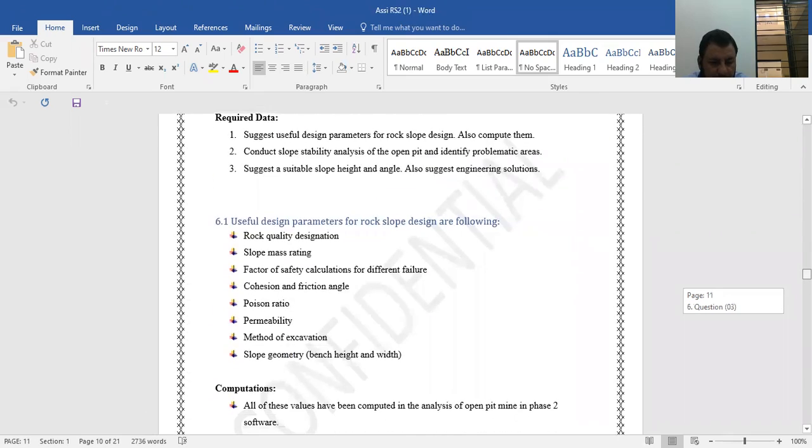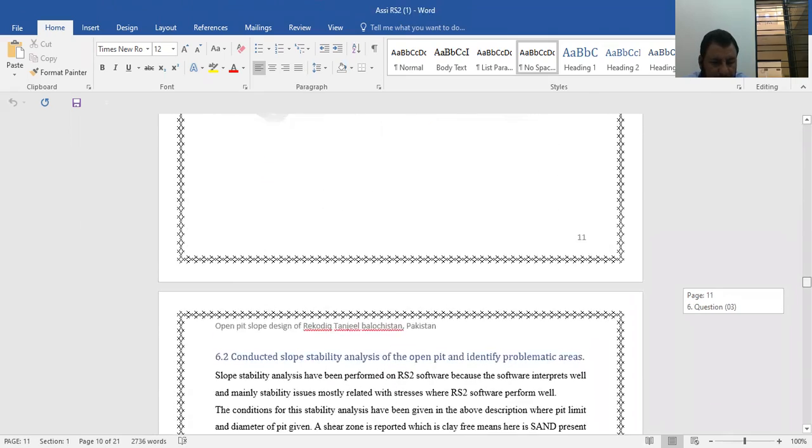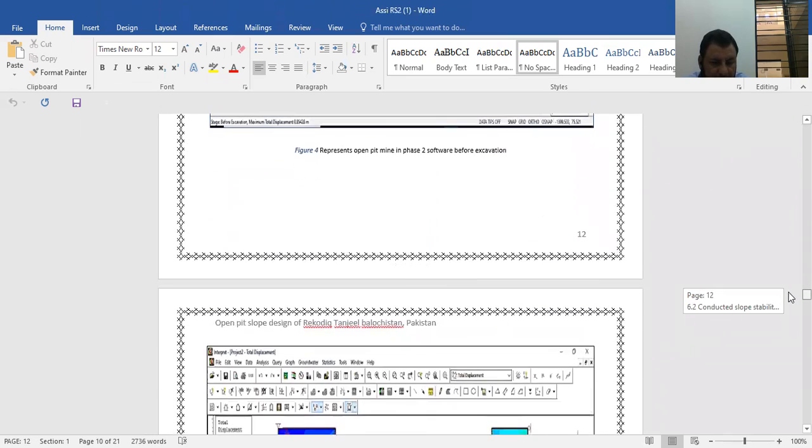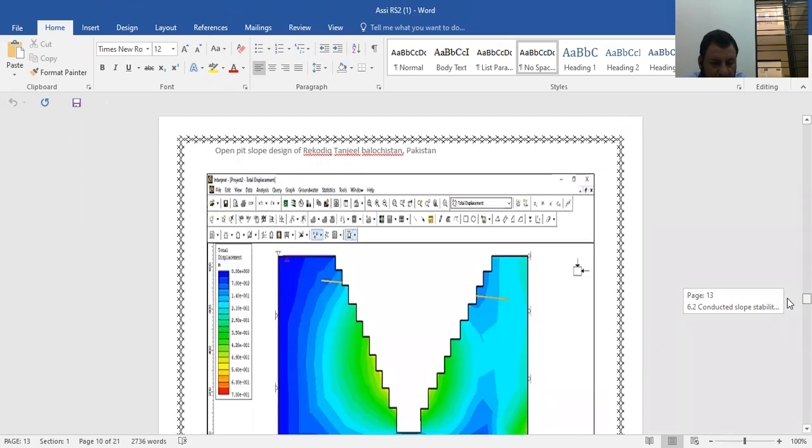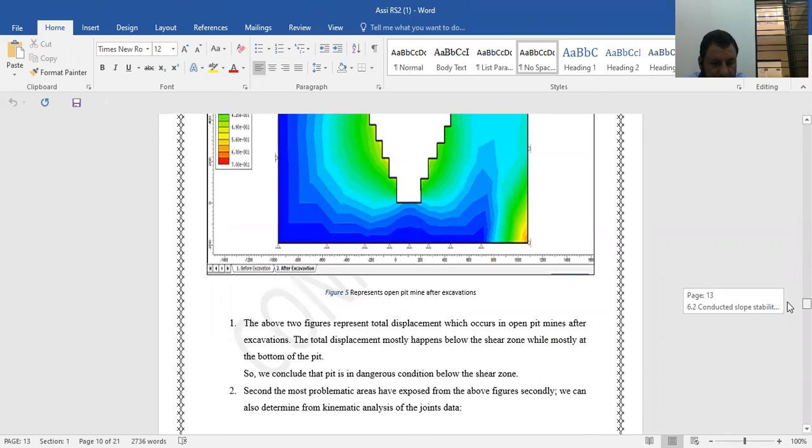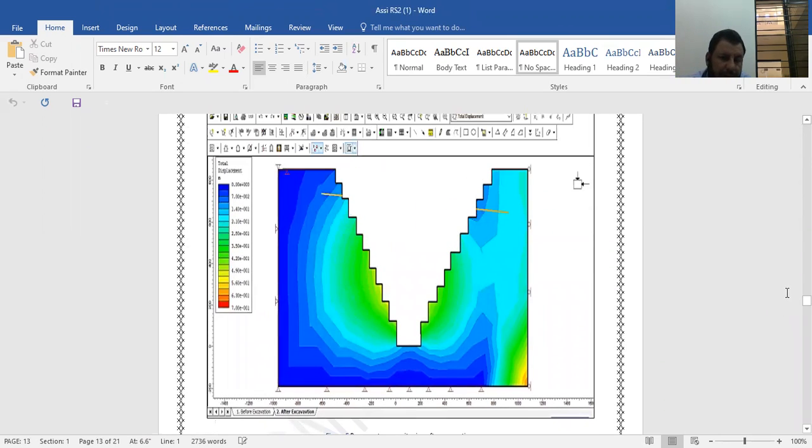The open pit mine should be excavated with great care below the shear zones, and secondly, benches should be left with greater dip directions, because at 60 and 65 degree dip directions there is a chance of planar and wedge failures. So benches should be extended with specific dip directions greater than 120 degrees. If the overall slope angle increases, the possible extent of the development of any failure to the rear of the crest increases, and it should be considered so that ground deformation at the mine area can be avoided.